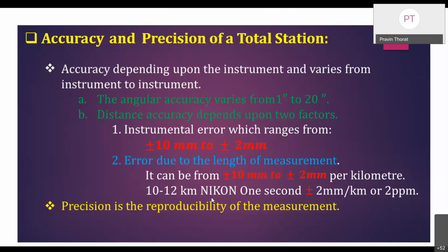The distance is determined by emitting and receiving multiple frequencies and determining the integer number of wavelengths to the target for each frequency. Most total stations use a purpose-built glass prism reflector for the EDM signal and can measure distance to a few kilometers. Reflectorless total stations can measure to surfaces reasonably light in color up to a few hundred meters.